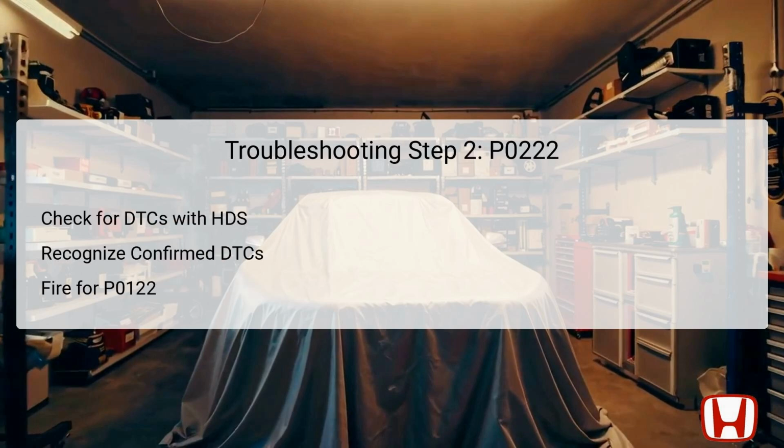In troubleshooting step 2, the focus shifts to examining any pending or confirmed DTCs using the HDS. At this point, you need to check specifically for any indicators of DTC P0122, along with P0222. If both codes are present, it suggests a probable link between the two sensor failures, allowing you to proceed to step 4 for further investigation.